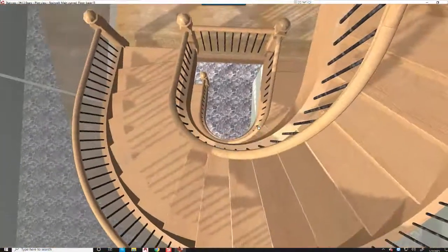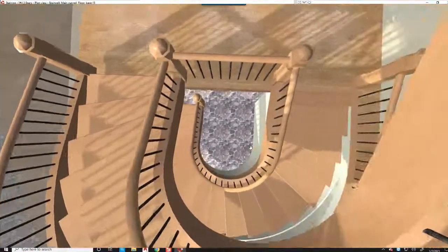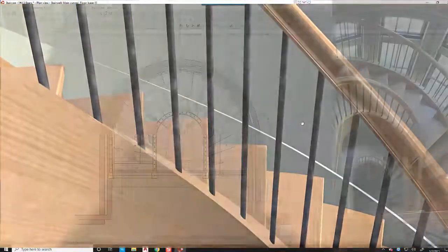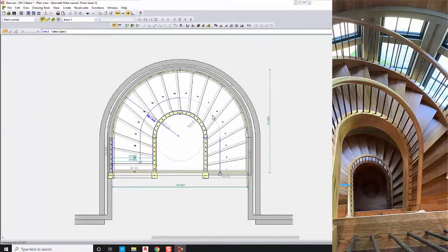We're going to show another project that has multiple levels of floor. As you can see, these treads are all askew, which really makes for a comfortable stair. The important thing with that is, you take a straight stair that an architect initially had, with three straight runs, then curves, and then straight runs, where the rail doesn't flow smooth and clean. It's very blocky, chopped up. You end up with odd winders. This makes the stair so that the path line, walk line, and pitch line, everything is very consistent.